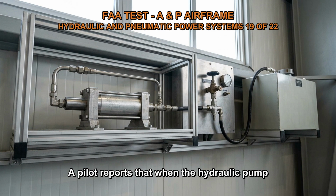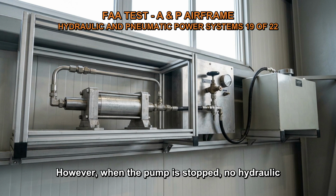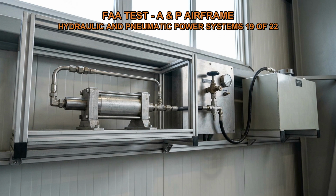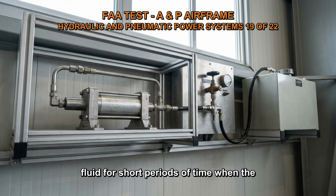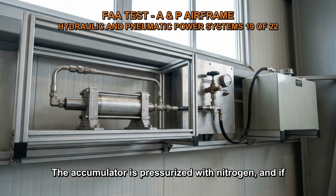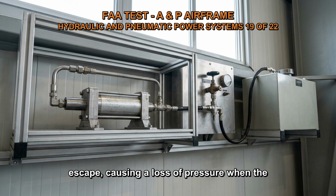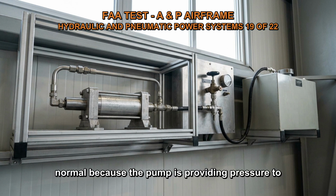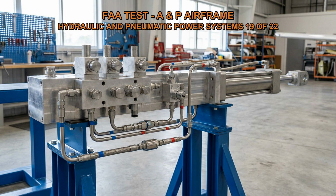A pilot reports that when the hydraulic pump is running, the pressure is normal. However, when the pump is stopped, no hydraulic pressure is available. This is an indication of a leaking accumulator air valve. The accumulator is used to store pressurized hydraulic fluid for short periods of time when the pump is not running, so that there is still enough pressure to operate the system. The accumulator is pressurized with nitrogen, and if the air valve is leaking, the nitrogen will escape, causing a loss of pressure when the pump is not running. When the pump is running, the pressure is normal because the pump is providing pressure to the system. Therefore, the correct answer is C.